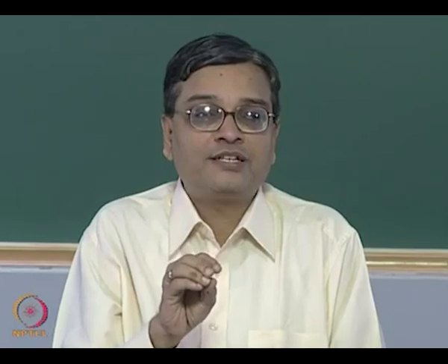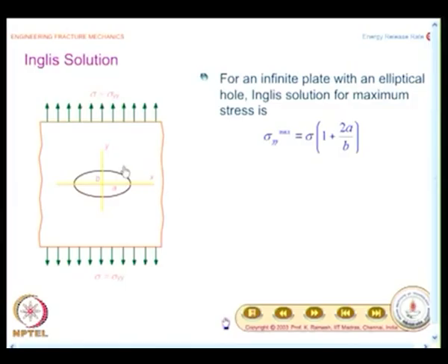Point number 2 is that the stress levels will increase, which was a recognition by the solution of Kirsch for a plate with a circular hole and Inglis for the case of an elliptical hole. And what you will have to realize is, suppose I do not have a cutout, when I have a uniaxial stress, I would still have only a uniaxial stress field in all the regions. The moment I bring in a cutout, the stress field changes to biaxial. This you have to recognize first.